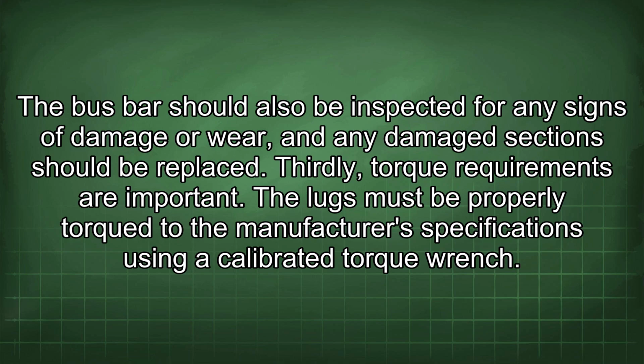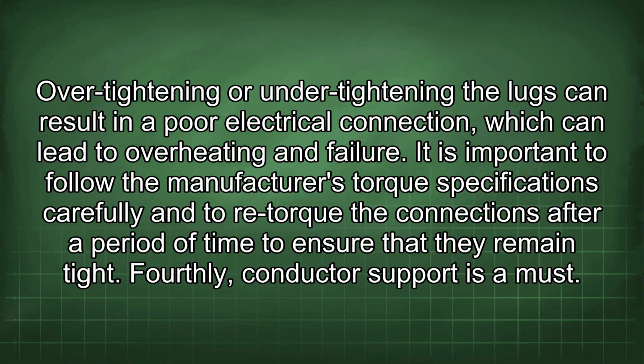Thirdly, torque requirements are important. The lugs must be properly torqued to the manufacturer's specifications using a calibrated torque wrench. Over-tightening or under-tightening the lugs can result in a poor electrical connection, which can lead to overheating and failure. It is important to follow the manufacturer's torque specifications carefully and to retorque the connections after a period of time to ensure that they remain tight.